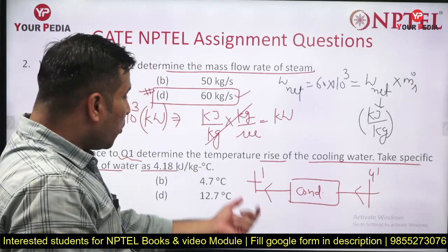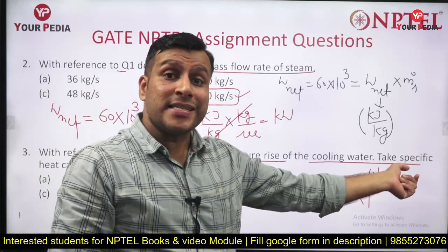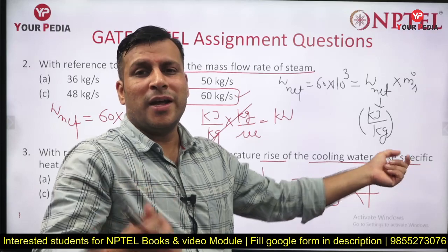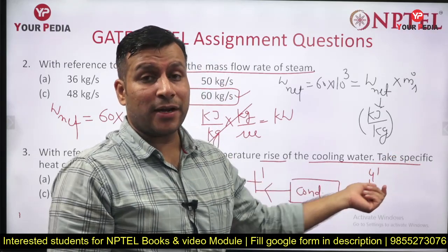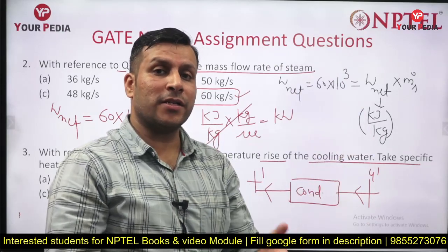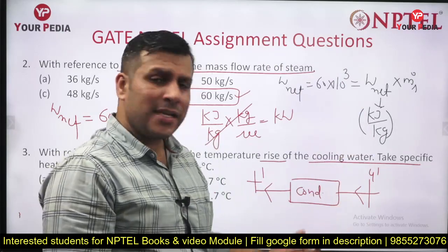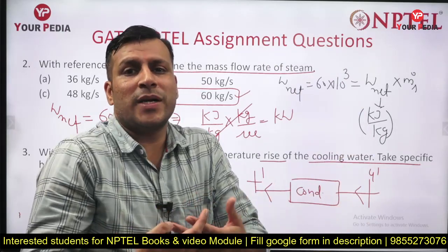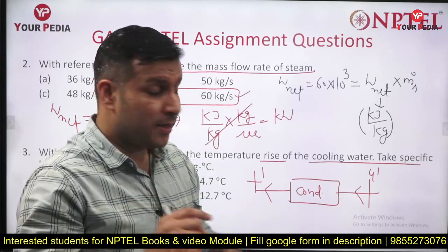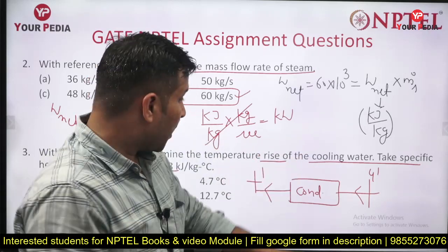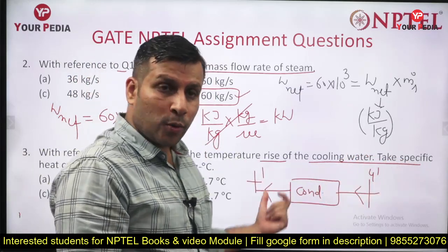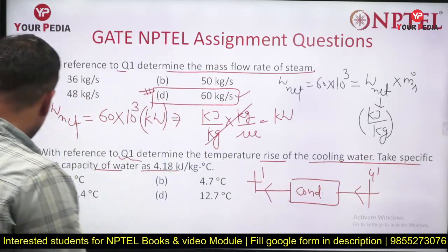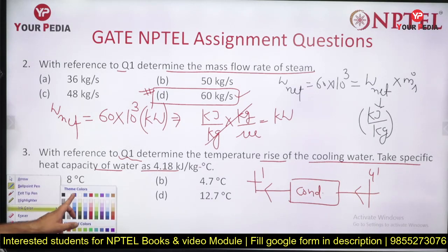But how are you condensing the wet steam? Most of the steam is dry, close to 82% of the steam is dry. The remaining is wet, but the mixture is in the wet region. That's why I am defining that steam as wet steam. So the condensation is taking place because the steam is converting into liquid. And how? Obviously you need to reject the heat to some water.